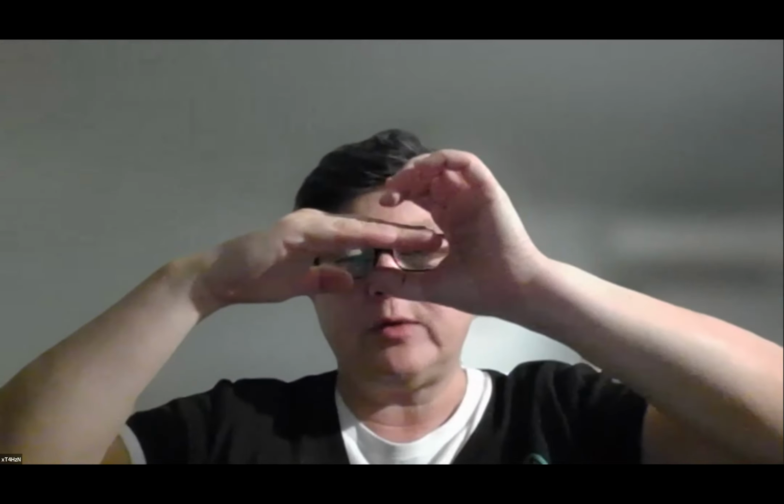So the temperature surface gun, if I point it to the surface, I will actually see a dew point, because the temperature within this space here and the temperature within the space that is impacted behind where the concrete is cold, it will create a temperature difference. That temperature difference, if the material has 100% temperature differences, is what we call dew point, and that will happen. Even if it doesn't have 100% differences, it has enough for it to impact. You will then see that there's a possibility of mold growth.